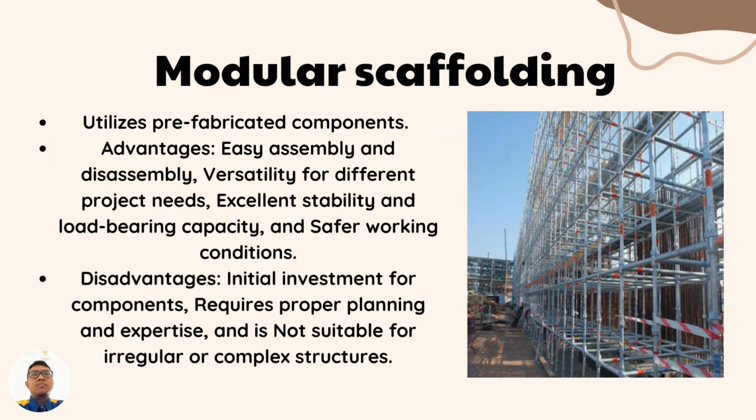And lastly is the modular scaffolding. It utilizes prefabricated components. Advantages: easy assembly and disassembly, versatility for different project needs, excellent stability and load bearing capacity, and safer working conditions. Disadvantages: initial investment for components, requires proper planning and expertise, and is not suitable for irregular or complex structures.